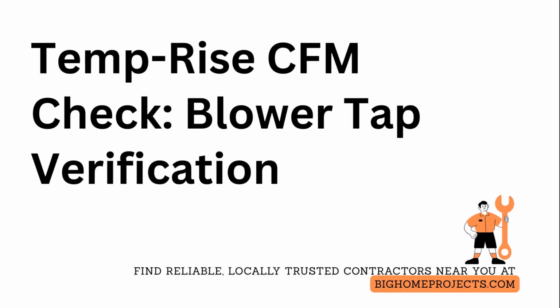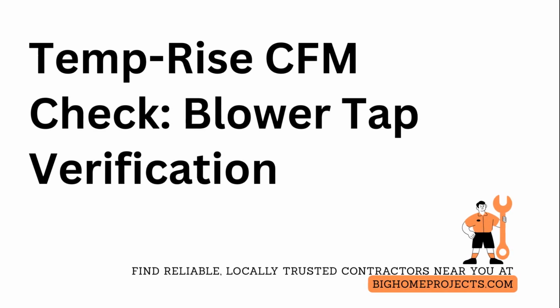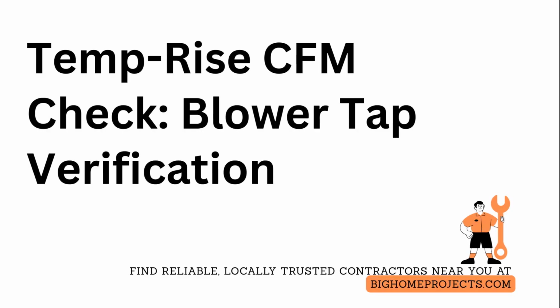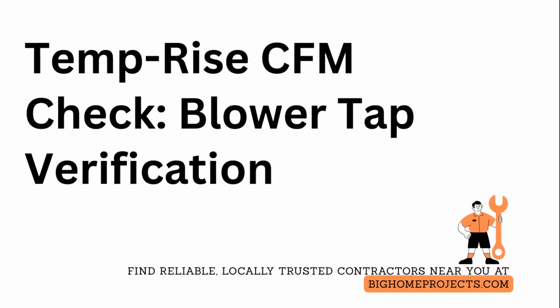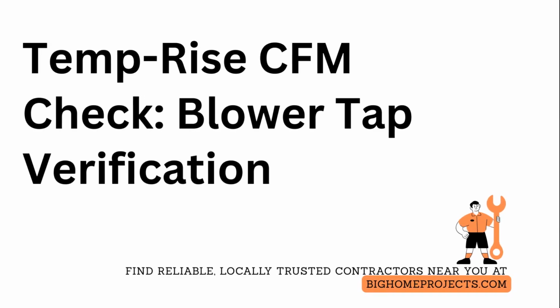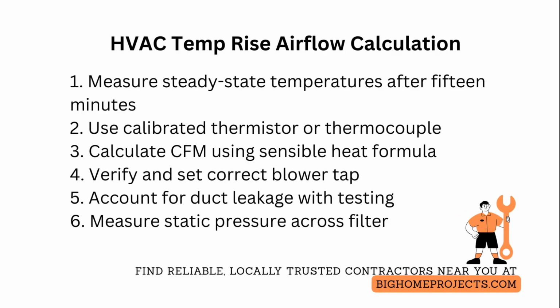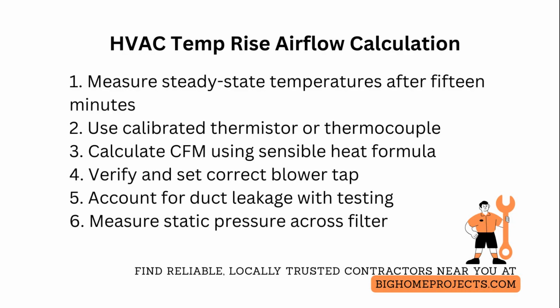HVAC Temp-Rise formula lets you calculate actual airflow in cubic feet per minute by measuring supply and return temperatures and applying a simple, repeatable equation. Measure steady-state temperatures after 15 minutes of operation with the system set to the exact fan speed tap you intend